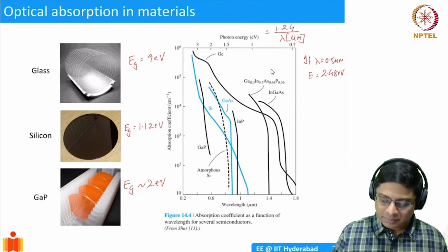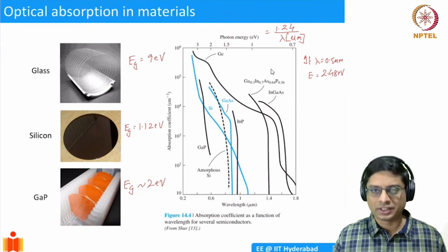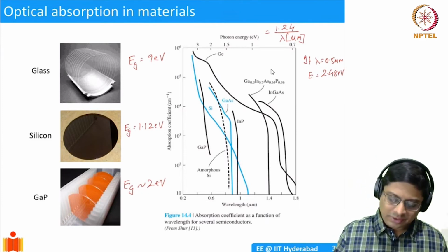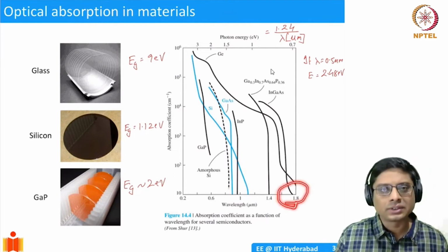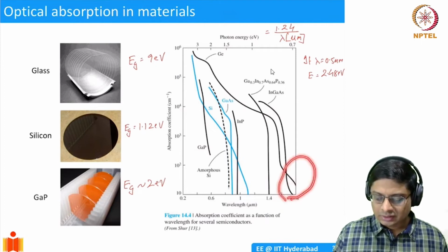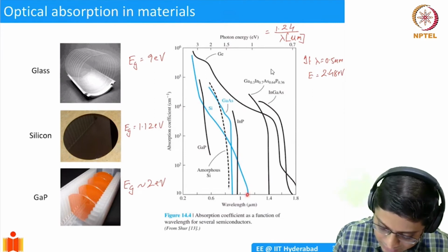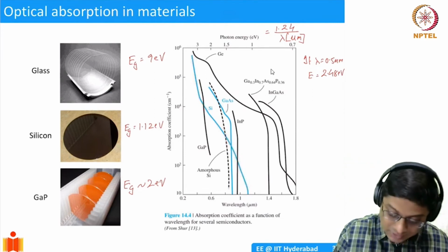And this picture here on the right is showing you the absorption coefficient for various semiconductors. So you notice some trends here, which is that all the materials have low absorption at long wavelengths. All of these materials shown here. And let's take the familiar one, which is silicon. Silicon is shown in blue here. So absorption is increasing. And this is a logarithmic scale, remember.